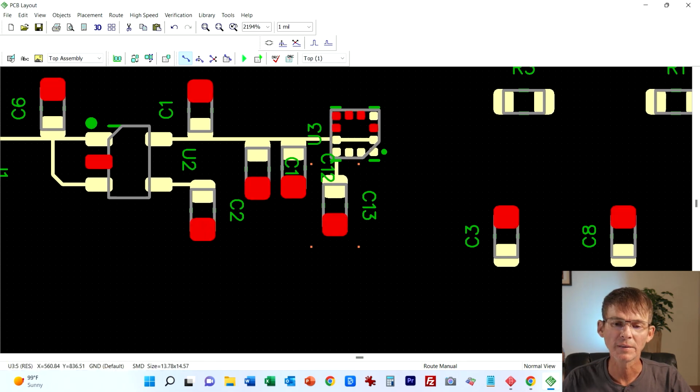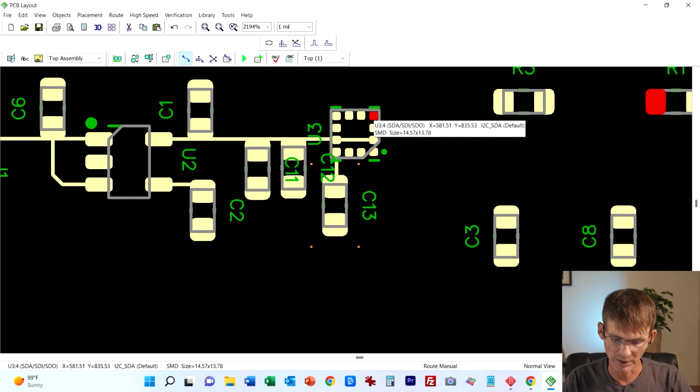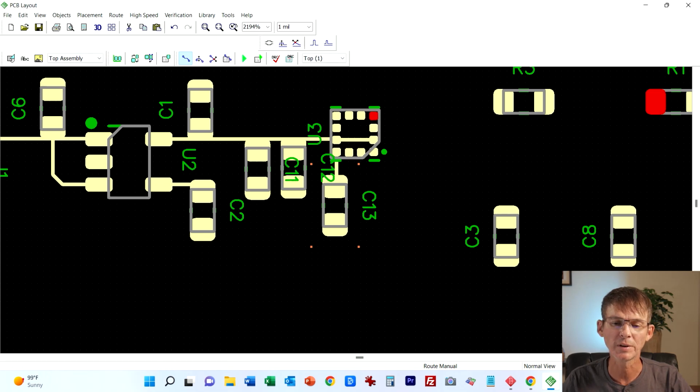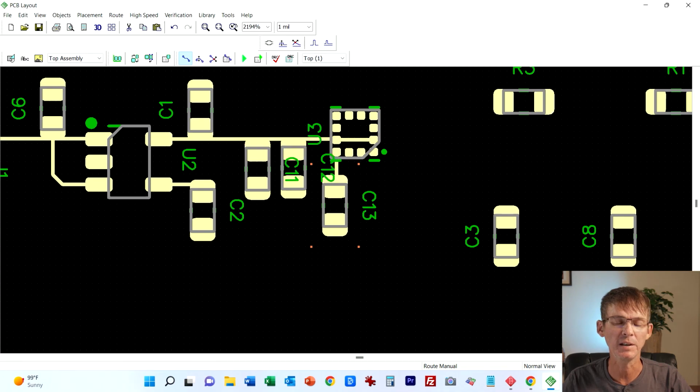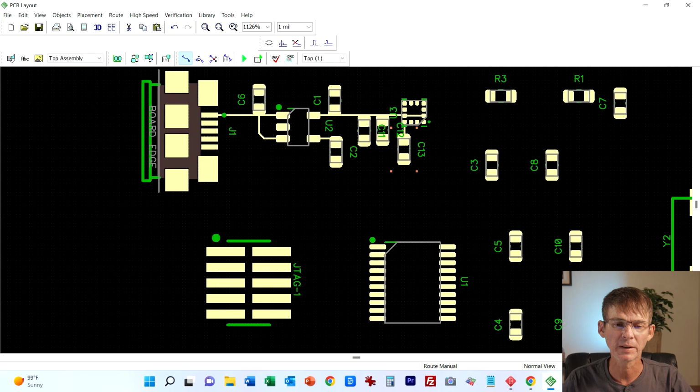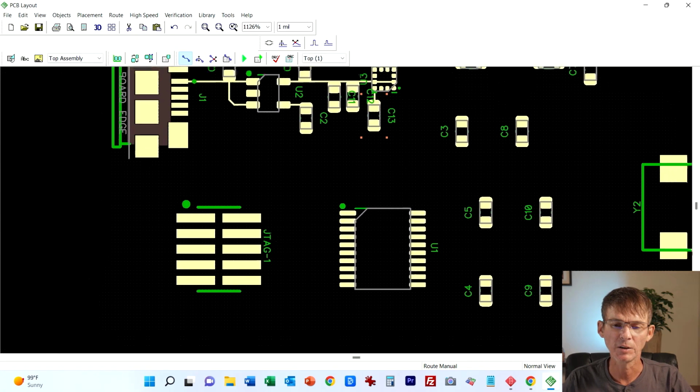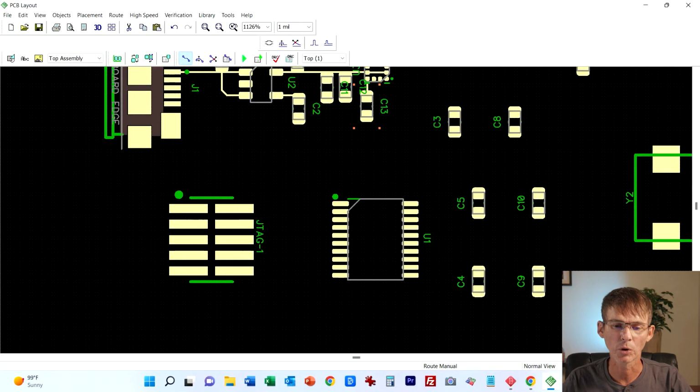And then the only thing left is the ground pins. We'll do that with the ground plane. We have this pin here. This is the I2C. We'll do the I2C connections later. I just wanted to get basically all the power in, and some of the localized connections, like connecting up the enable pin or the chip select pin. Okay, so now we've got the linear regulator and the accelerometer. Let's go down and do some work on the microcontroller.